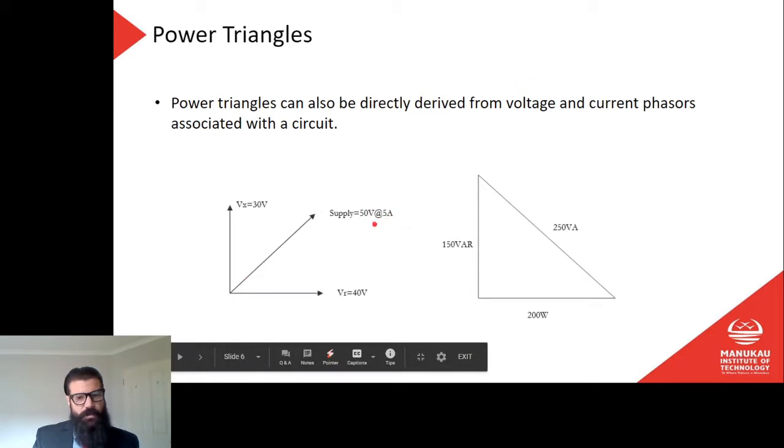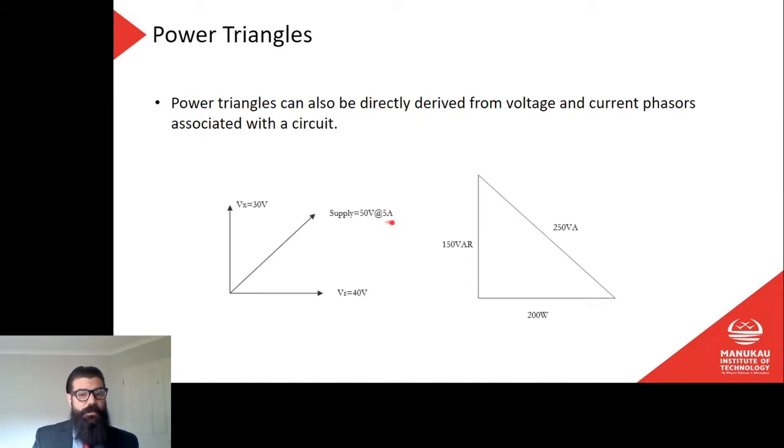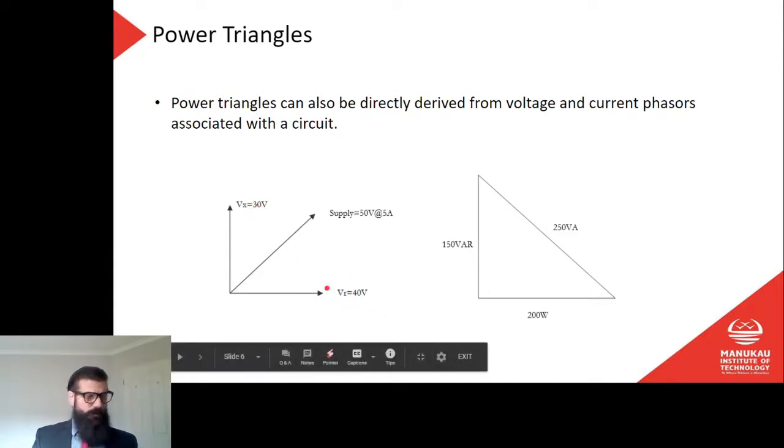And then we see there that we've got 5 amps flowing in a series circuit. 50 volts total, 30 volts reactive, 40 volts across the resistive component. So then volts times amps is my power, right? So 5 times 30 would be 150 VAR, that's my Q. My true power here, 40 volts times 5 amps in that circuit would be 200, and there I have that. And then obviously supply voltage is 50 volts, that's there.